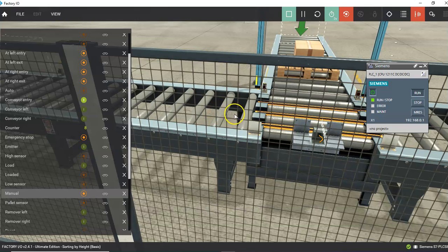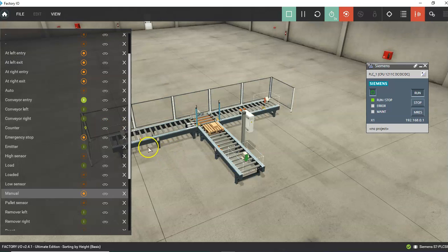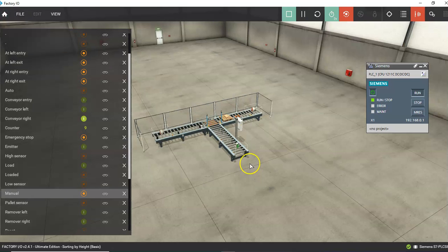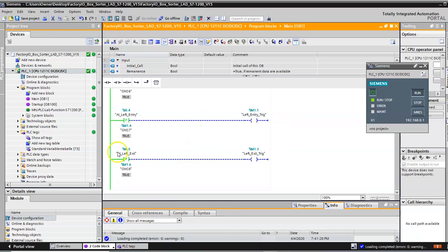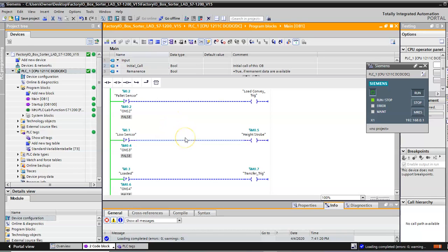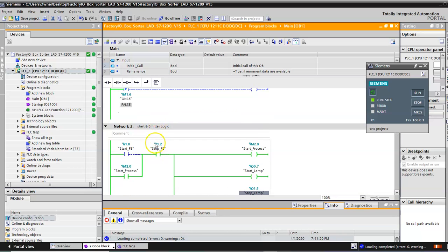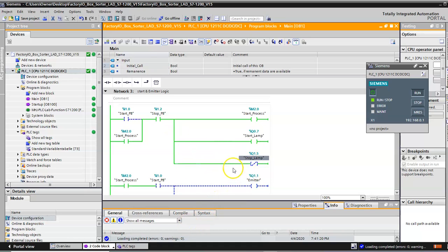So anyway, that's the first of three. The next one we'll do function block diagrams. What we're going to start out with is we're still going to keep all these triggers in. There's no reason to get rid of them. And actually, when you're combining logic, you're going to have some that's regular ladder logic, and some that's function block. But the next part of it, we're just going to get rid of all these networks from after the edge triggers, and we're going to make all of these in function block diagrams.